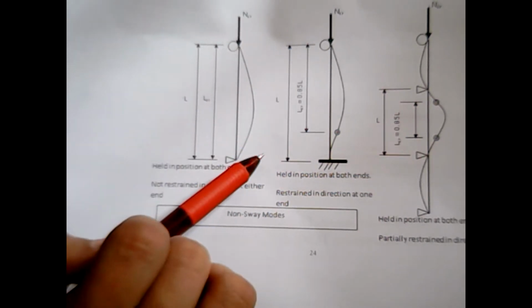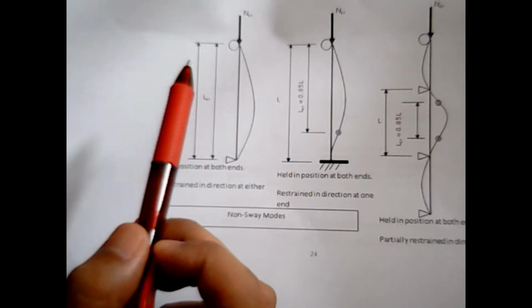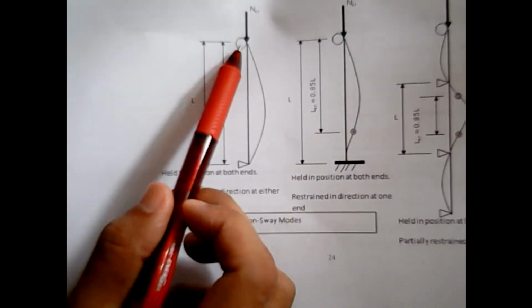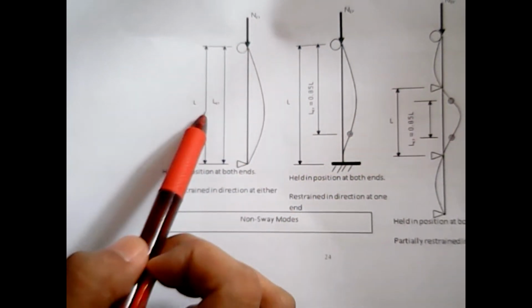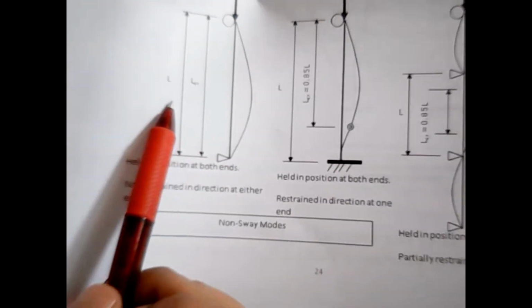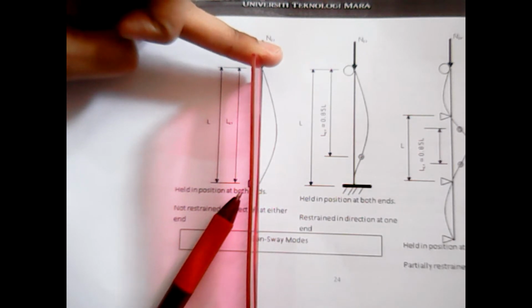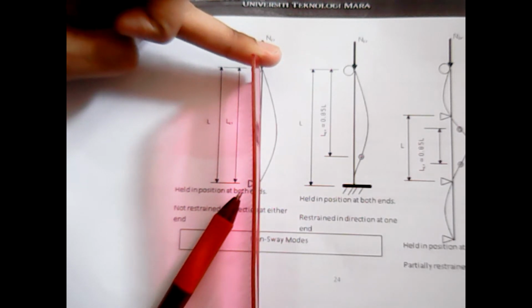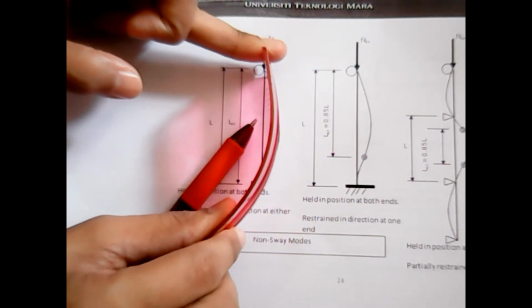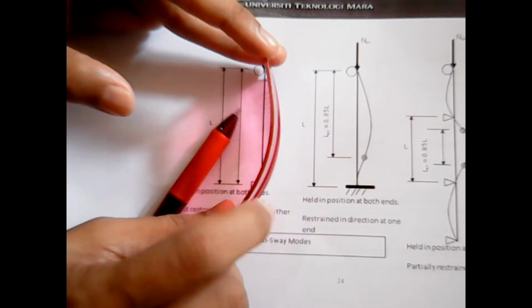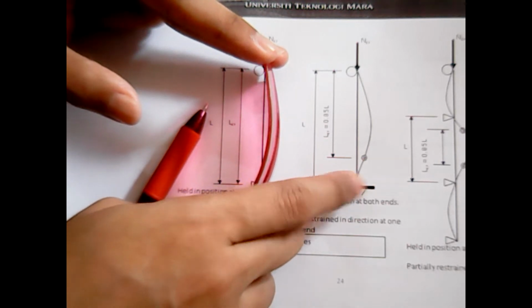Both ends are allowed to rotate. Because both ends are allowed to rotate, your effective length or critical buckling length is measured from the point where the column rotates, which means your LCR is equivalent to L. We restrain it laterally like this and allow for the rotations. If I pull here, it is able to rotate from this distance to this distance. It is able to rotate. But if you look at the second case,